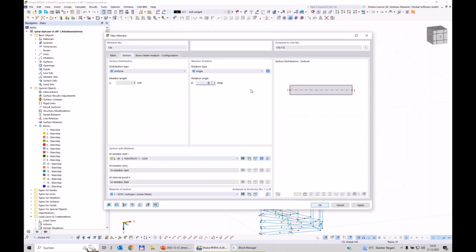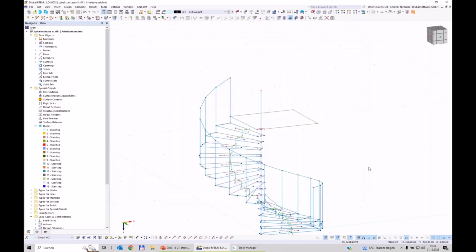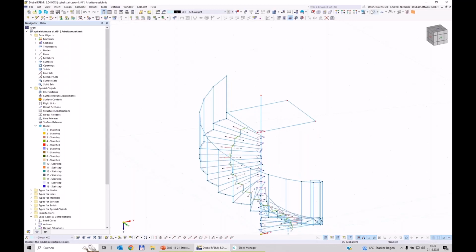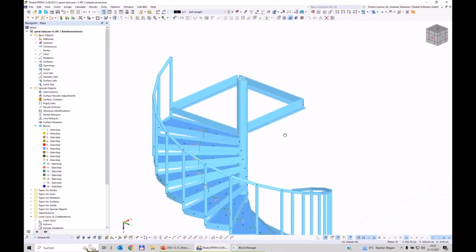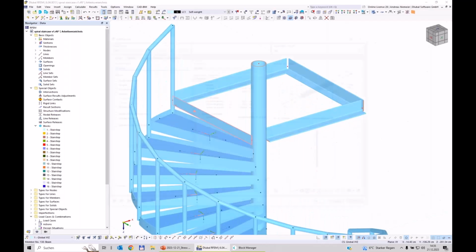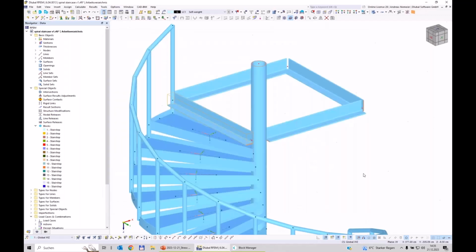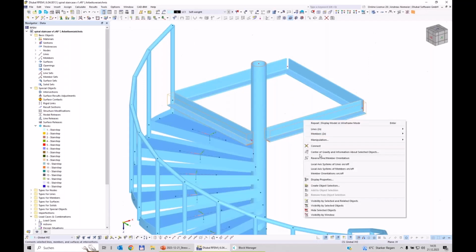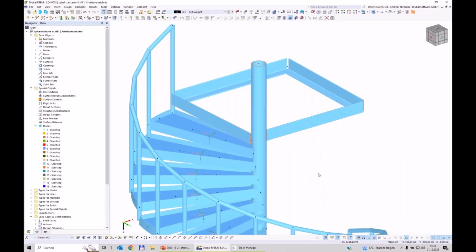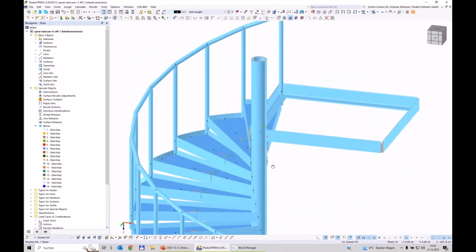And now we can remove this rotation, and these lines get blue. You see, maybe this front member we can change also to the same section. It should be this L section. But the flange should show inside, so we take both and reverse orientation. And now it fits almost.